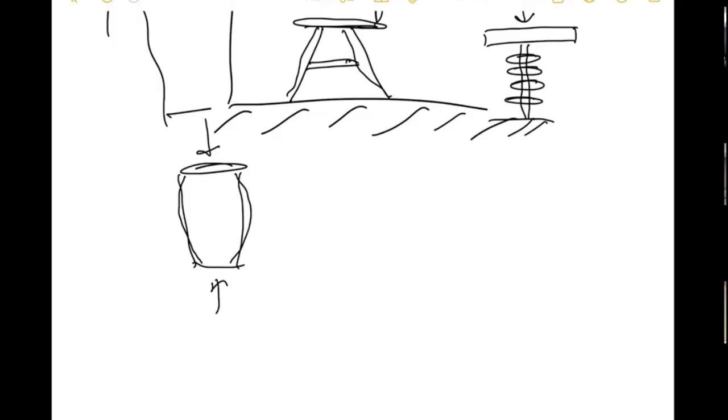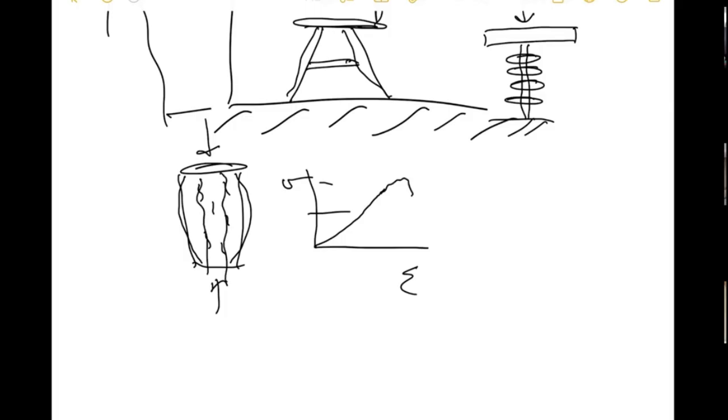It naturally does. And that's part of the reason why you get these cracks that form in this direction. And eventually, when you do a stress strain curve, they go up and you start getting all this cracking here. And then eventually it breaks, and it tends to break into big pieces. They call this axial splitting.